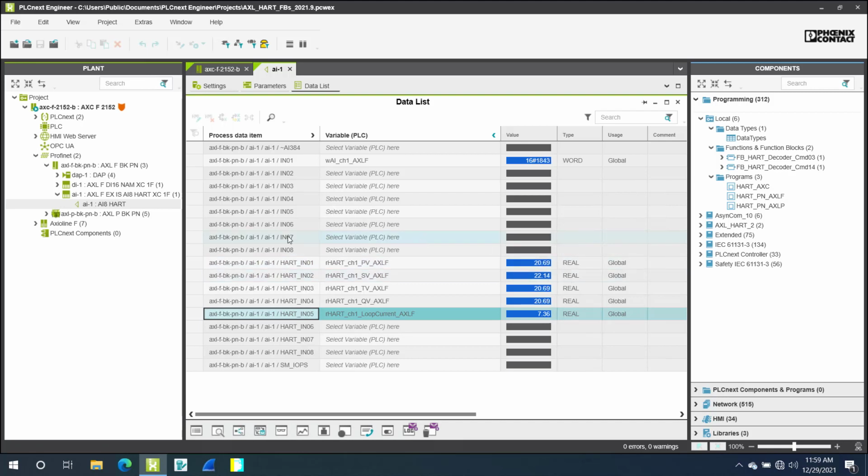So that's pretty much it. This is how it's done in Profinet for a Profinet bus coupler. For Modbus TCP, Ethernet IP, Profibus, it's a similar setup. It depends really if you're using a device description file like in Profibus and Profinet, or in Modbus TCP if you're just pulling registers. Again, you're just going to get your process data however you normally would in that protocol. So let's go back and look at the third HART module for Axial Line P.